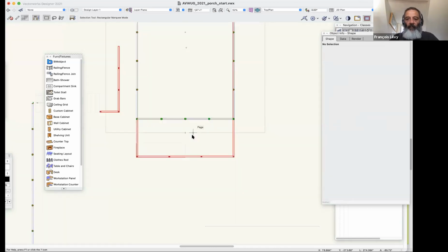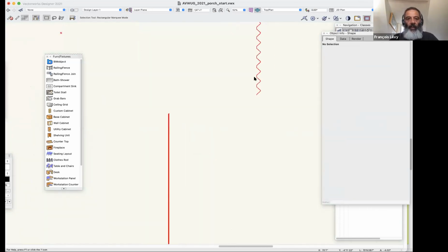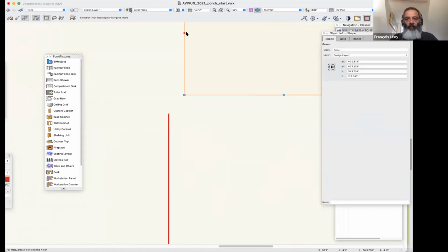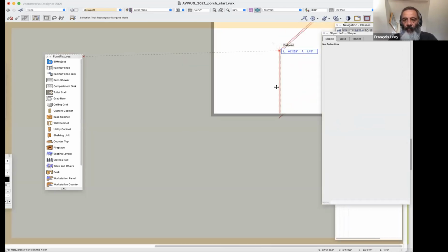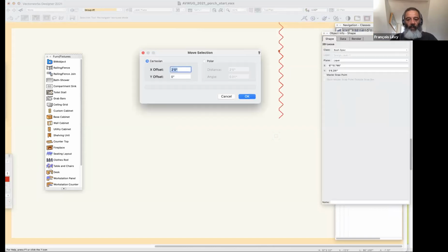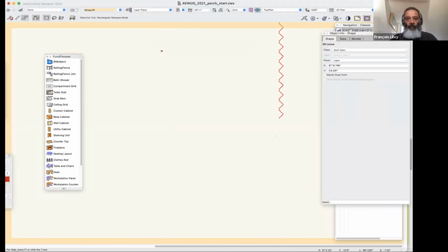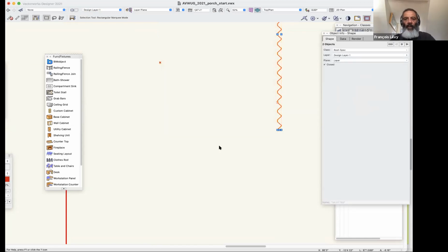So I'm just going to go back here to top plan view and go back to my corrugation here. And I'm going to grab this little 2D locus. Oh, it's in a group. Sorry. I'm going to grab this 2D locus and just pick an inside face, say right here, whatever. And move it to the left 24 feet. And then I will select the profile and the locus, and let me exit the group and ungroup this because it may not play nice in a group.